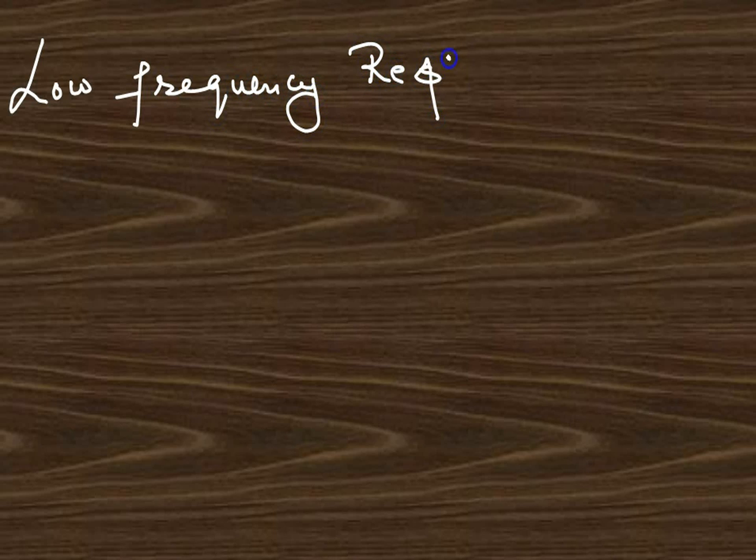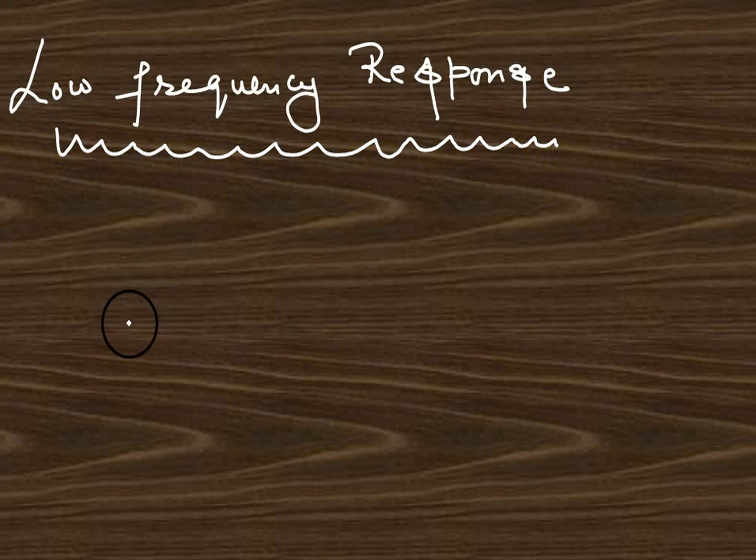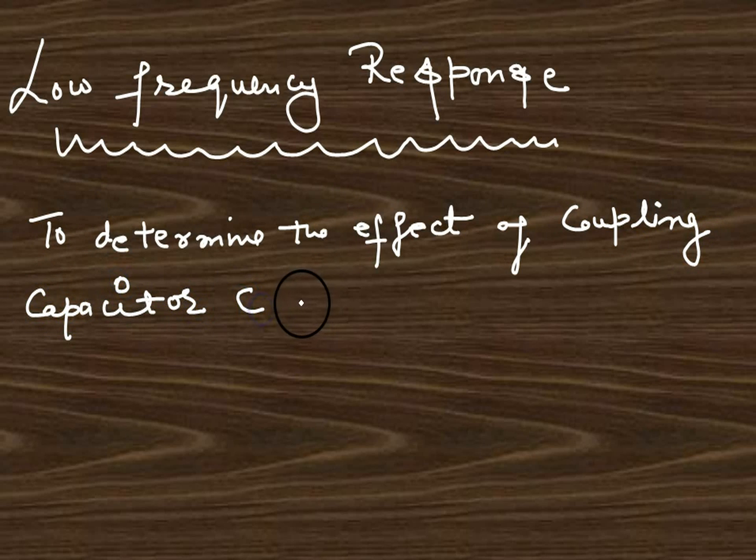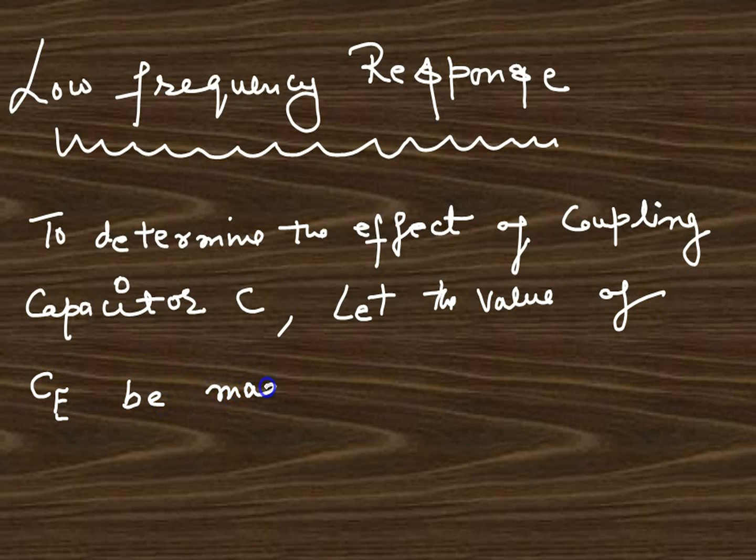So we want to analyze the low frequency response of this circuit, how this circuit responds to the low frequencies. And what is the effect of the coupling capacitor C? This is very important. There is another capacitor across the RE, that is named as CE.